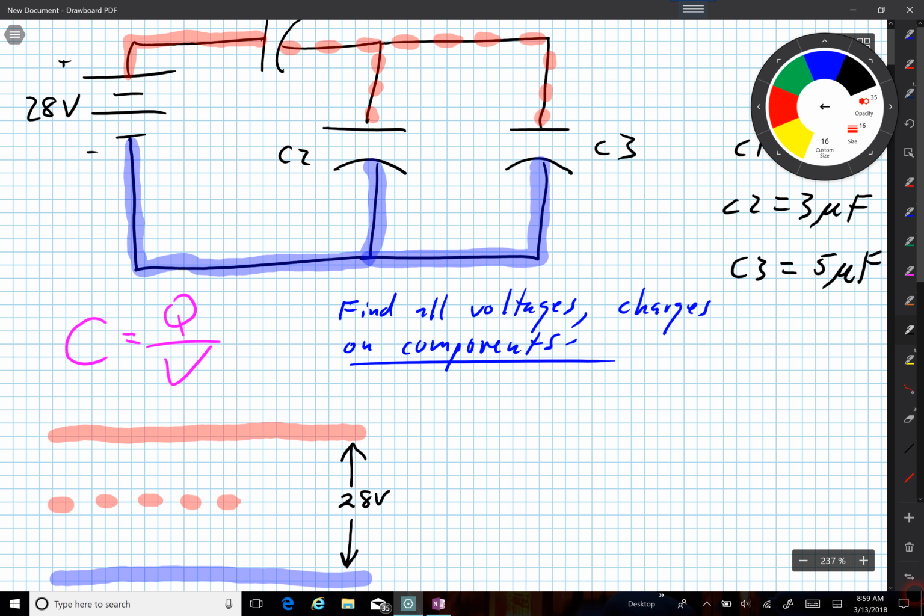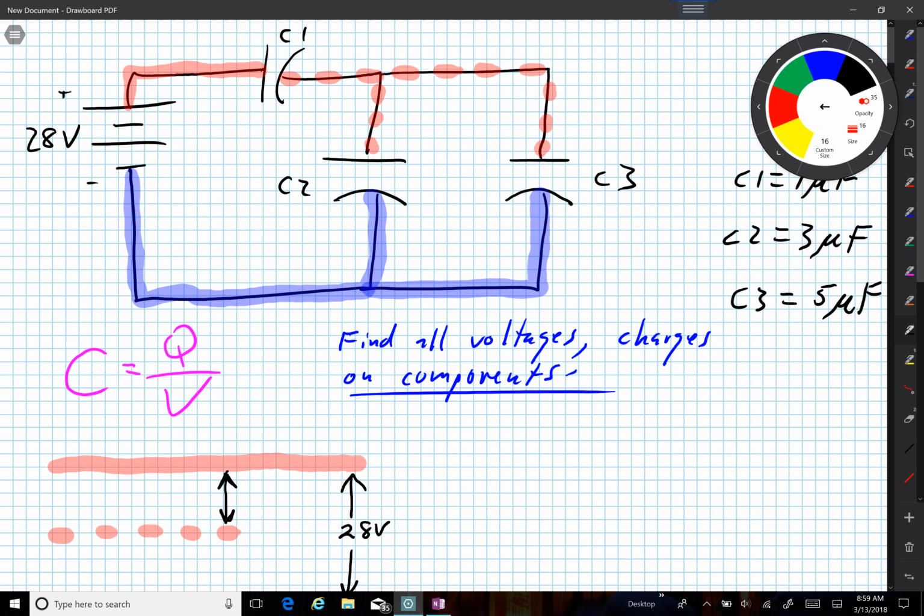Okay. And then we have a voltage here, which is solid red to dashed red, and I can see that color combination right here on capacitor C1. It's the only component that has that color combination. And remember, it's two colors. Each component has two wires going to it, a wire coming in and a wire going out, and I have to look at both wires and look at the color and style of the lines for each wire, and it's the combination that I'm interested in.